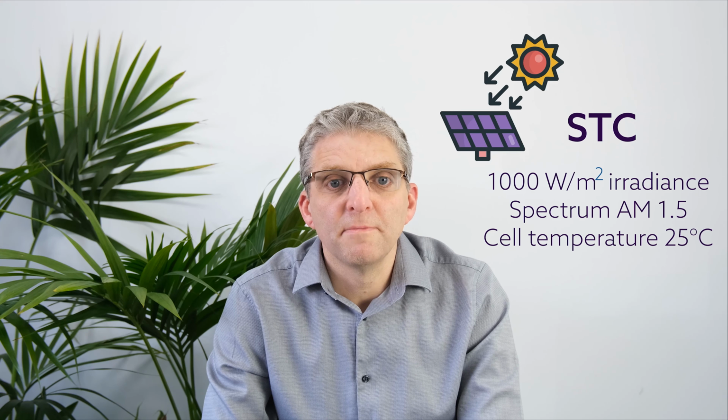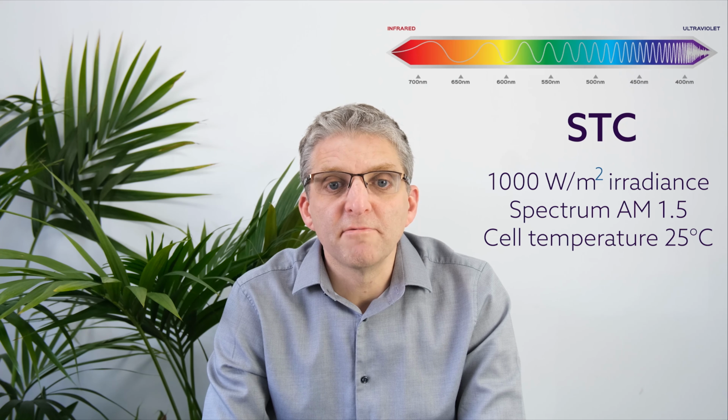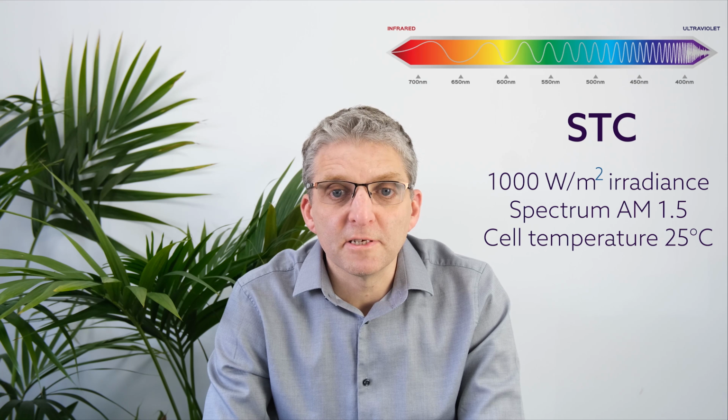They're mentioned on every solar module datasheet, and the standard test conditions include the level of light, which is called the irradiance, the spectral composition of the light, in other words, the relative level of each component wavelength of light from infrared through to ultraviolet, and the temperature. All of these things have an effect on solar performance. Standard test conditions are equivalent to a clear, bright, sunny day, but because the conditions are so specific, they can't be replicated easily, and they rarely occur naturally.